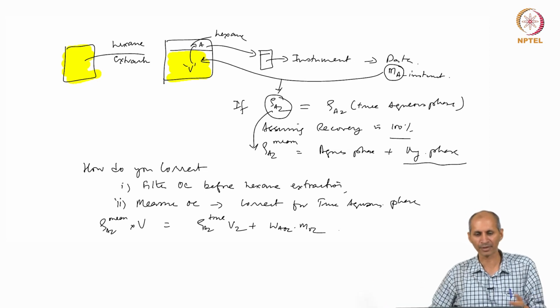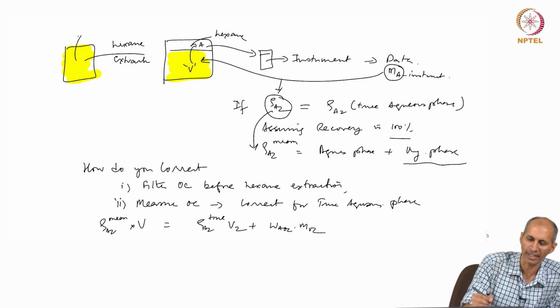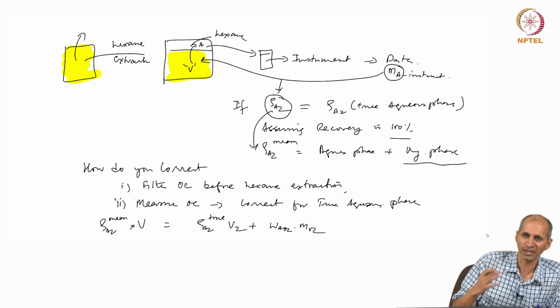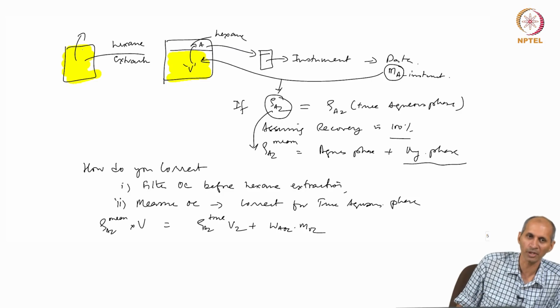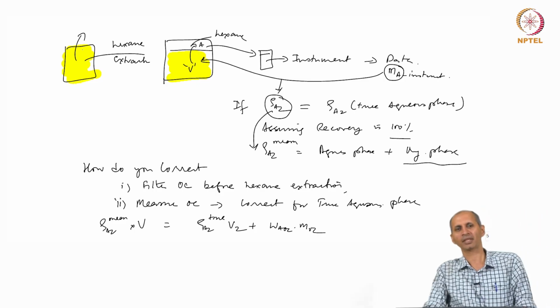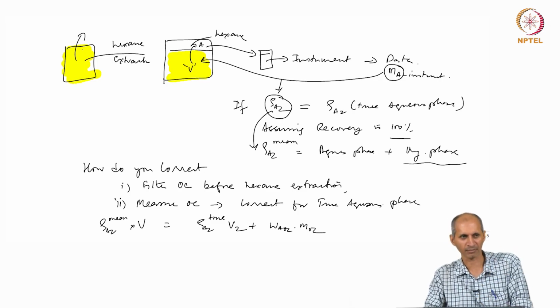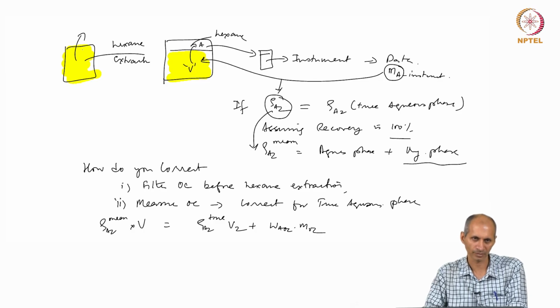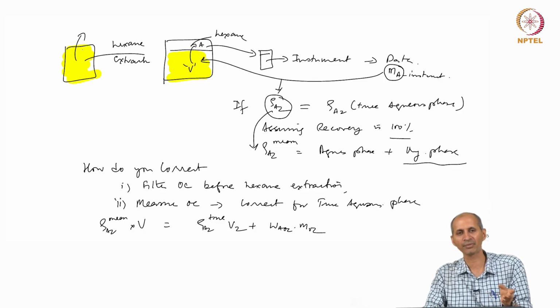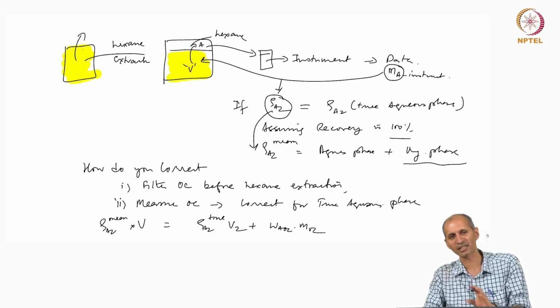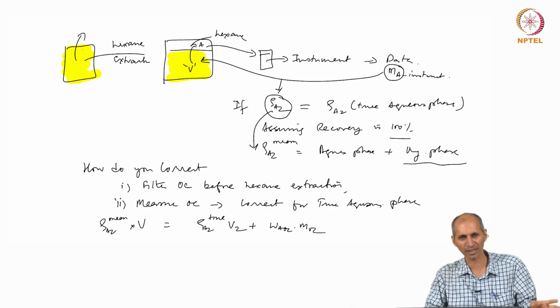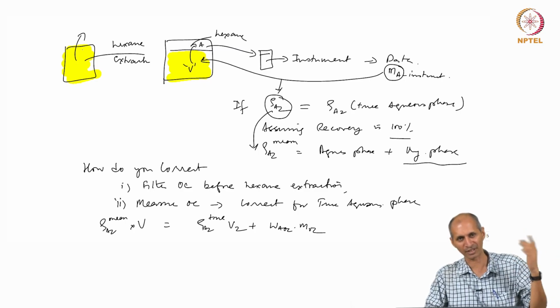For example, if somebody is supplying this water for drinking, you are drinking everything, your intake contains everything. So then you may not want to correct for it, you may want to actually measure the total concentration here along with the organic carbon, which you can't see sometimes. The water sample will look almost clear, but it may contain a very small amount of organic carbon. If you are not having a filtration mechanism before drinking water, whatever I am unable to filter, I would like to measure the concentration of that, including the organic carbon also.